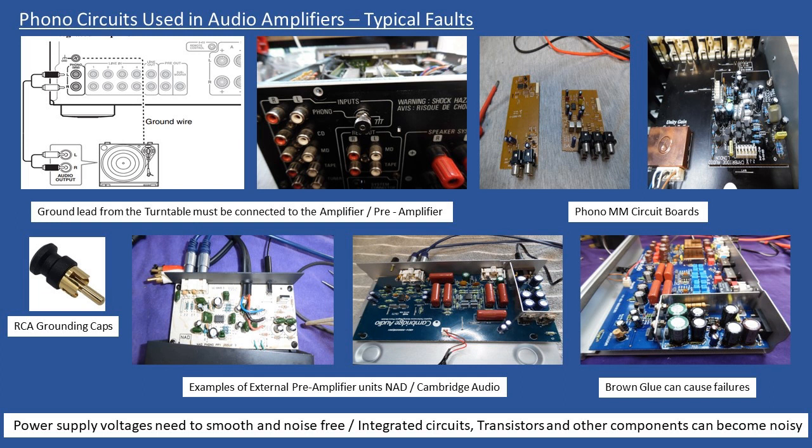You'll also see when engineers design the circuit board layout, they pay a lot of detailed attention to where these copper tracks go and where the ground connections are, because what they want to do is minimize the signal paths as much as they can, and really that helps to reduce overall noise being induced into these preamplifiers and main amplifiers as well.